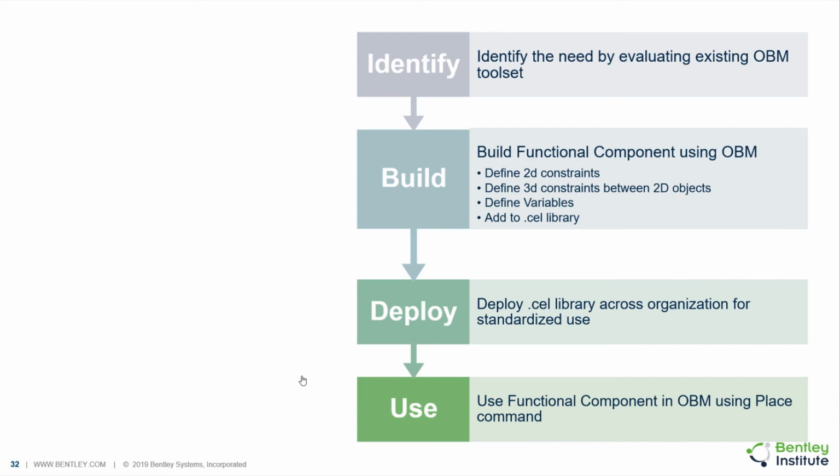But this parametric cell means that some of the dimensions could change by hand, right? And so then you can just type the new dimension and the cell, the cap may get longer, wider, deeper, or the column as well. So you will apply certain constraints to the MicroStation cell that you are creating and just save it in OpenBridge Modeler as a cell library. So you deploy it, and basically what you create is a set of cell libraries with all these parametrics included.